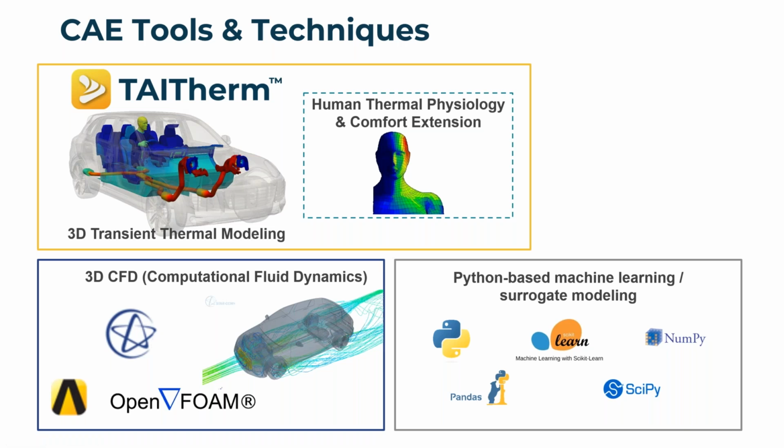transfer. We'll be using a CFD model for the cabin interior air to represent the flow field distribution and modeling how the flow boundary conditions coming from the HVAC system interact with the cabin. Our demo models are going to be using StarCCM+, but everything we're showing could easily translate to other CFD tools that are supported in CoTherm.